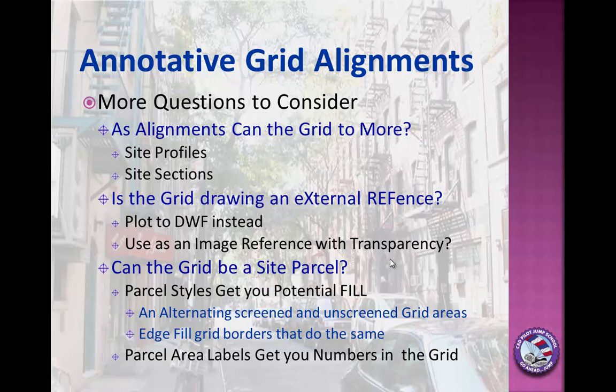Do you want the grid drawing as an external reference? Most certainly. A couple of things that we probably want to do before we're done with our grid drawing is remove the reference surface so we only have the grid, get rid of all the other miscellaneous styles we are not employing, and clean the drawing up, make sure it's as thin and lean as possible and not going to cause me performance issues when I plot.